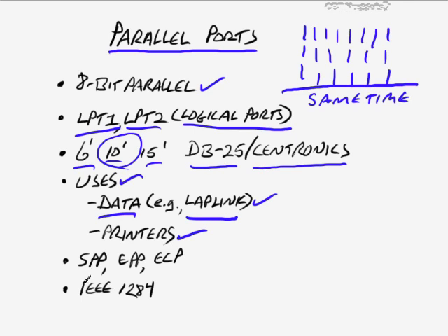There's a few different kinds of parallel ports. One of those would be a standard parallel port. This is generally considered unidirectional, even though it's got technical capabilities that allow it to both send and receive data. It can only do one or the other at a time. It cannot do sending and receiving simultaneously. And then a modest improvement over SPP would be the enhanced parallel port, and what this does is it just provides a faster speed than we could have with a standard parallel port.